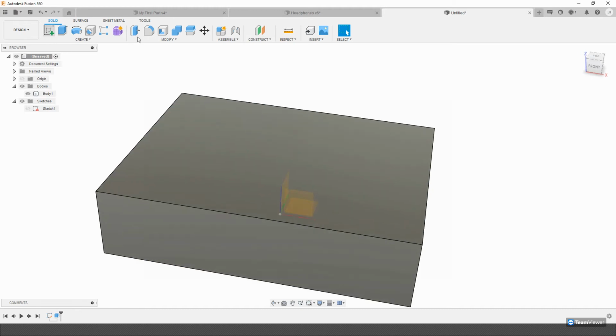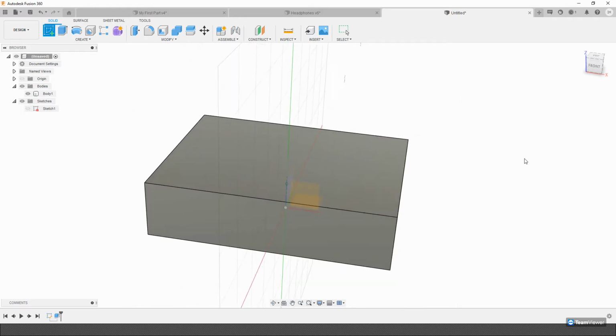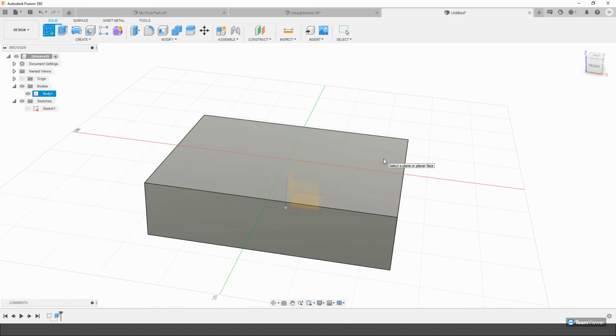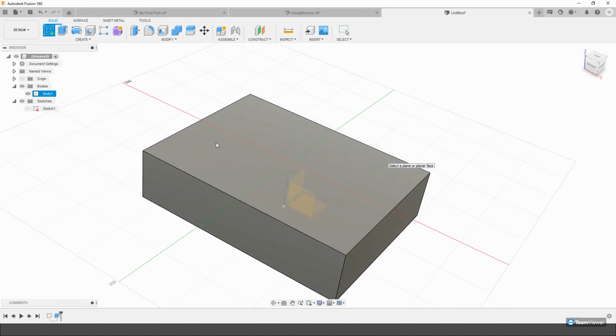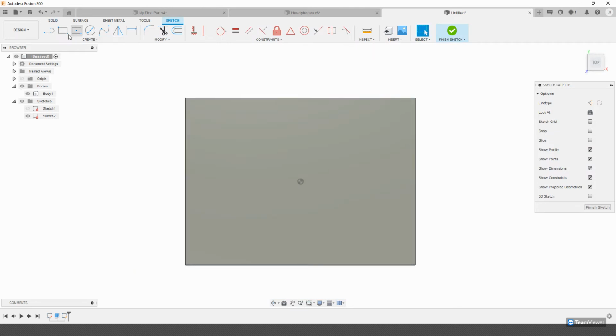Now, parametric modeling, we said that parametric modeling means that everything's based on features and constraints. So I can do, for example, another sketch, right? But I can now reference another face. So in this case, this face, the top face, and I will just give myself some guidelines before I begin. And you'll see why I'm doing this just now. I just made a little light construction line there. And now what I want to do is just draw some shapes that I want to cut out.